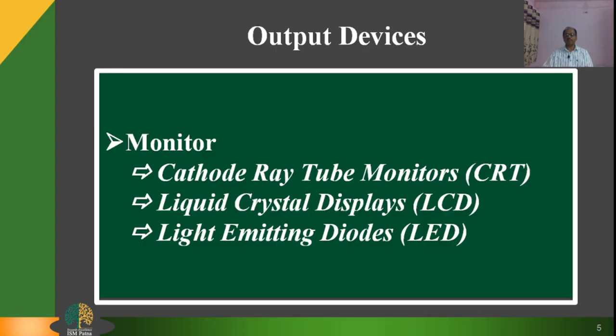The main components of a CRT monitor are the electron gun, the electron beam controlled by an electronic field, and a phosphor coated display screen. In CRT monitors, the image is projected on the screen by directing the electron beam onto the computer screen. Copper steering coils are used to create a magnetic field inside the tube. By applying varying voltage to the copper coils, a beam can be positioned at any point on the screen showing the image of the object.